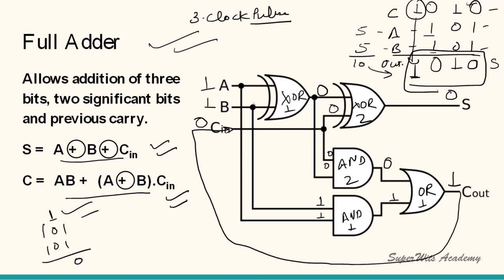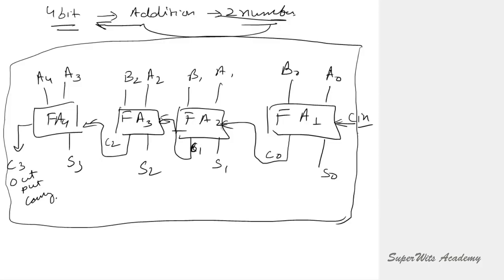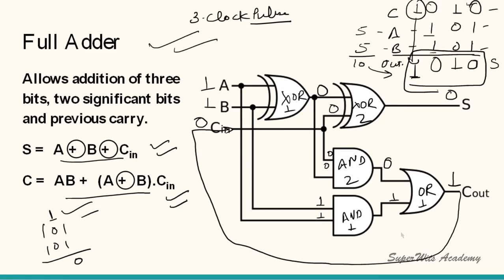by using a combinational circuit. Now nowhere here will you find a storage element, right, which is actually a flip-flop. We are going to discuss it in the next video, but there is nowhere we have storage. So what you do is you take the input, right, and you throw the output to the system, or maybe you feed it to the next combinational circuit, as we have done in this particular example. So the carry is fed into the next full adder circuit from each previous circuit, right? So this is how the combinational circuit works for your digital computer to process the data.